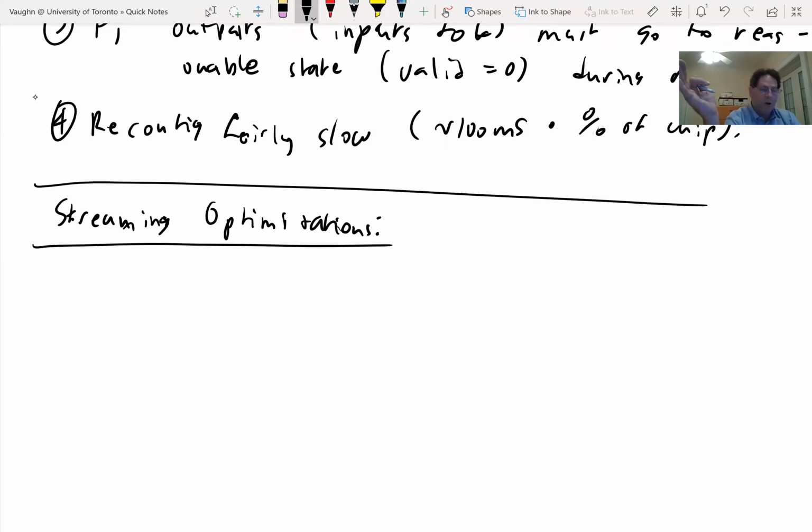And then within that module, you will often not have any back pressure, not have FIFOs, just have general pipeline registers, because once the data arrives, you're just going to compute. There are no stalls that will happen inside. So let's talk about optimization in streaming, because it is such an important data model for FPGAs.